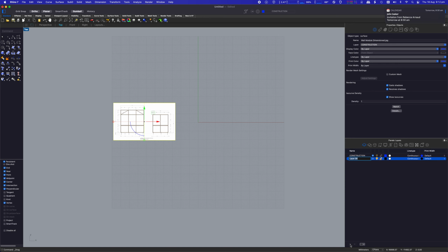The next thing I'm going to do is create a layer for my walls, and then under that layer I'm going to create 2 sublayers, one for symbolic walls, which will be just like a block, so that I can do a sort of schematic wall, and the other for the actual stuff with all the details in it. I'll call that complex. And that will do for now.